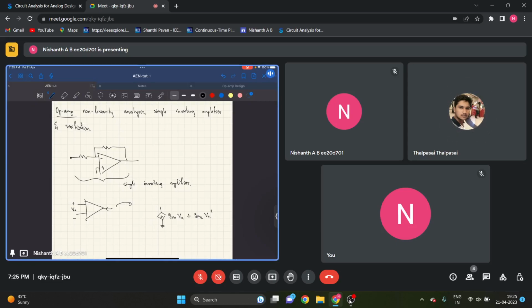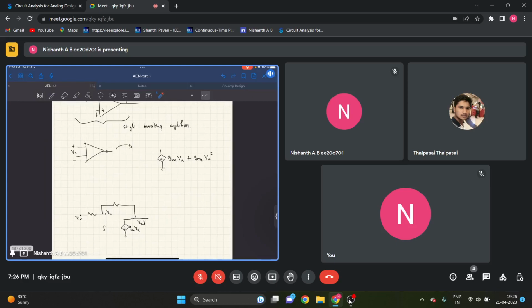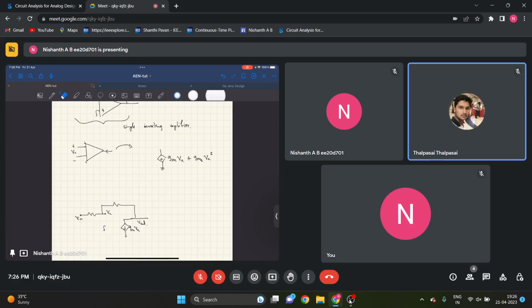Yeah, basically you'll have some non-linearity specifications. To match those non-linearity specifications, you have to choose a certain Gm. The choice of this Gm is what we will find with weak non-linearity, with the current injection method. Okay. Anyway, listen on if you have any questions.